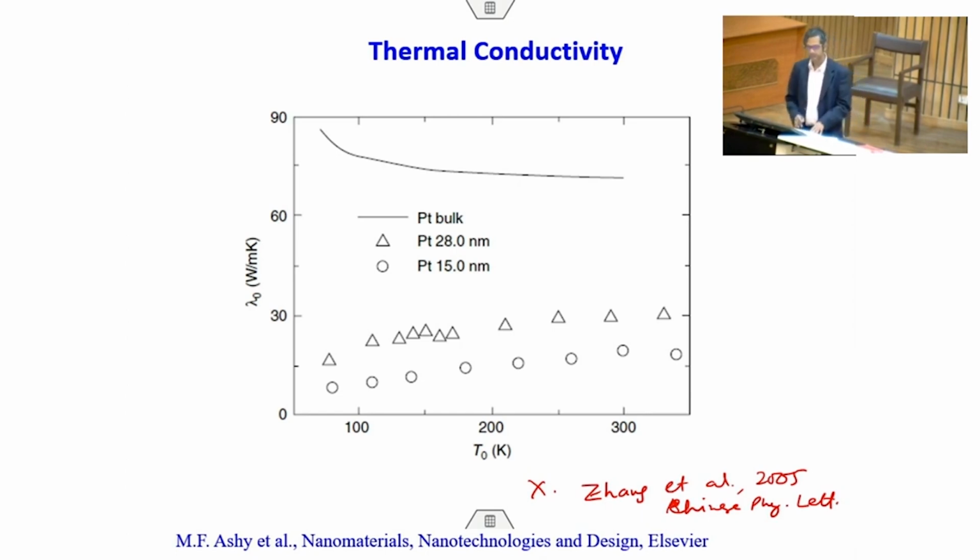That's very simple. As the thickness decreases, the energy levels get confined, and platinum is a metal, so the majority of transport will happen by electrons. Therefore electron energy levels get confined in the thickness direction, and electrons cannot easily move. Not only that, the moment you create a thin film, you have a large number of nanocrystalline or microcrystalline grains compared to the bulk, and these grains have grain boundaries. The grain boundaries will act as a scattering agent for the electrons.